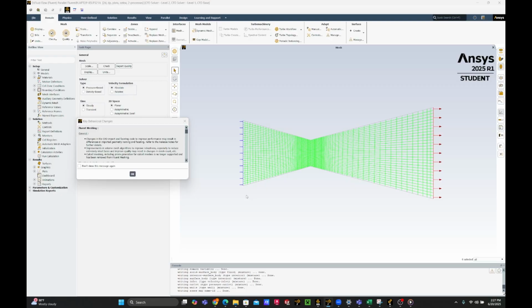Okay, perfect. And I know that this looks right because I have arrows going in and out, so that way I'm able to set up my pressure at the inlet and my pressure at the exit, and you can modify those. If you want a normal shock, you can just start increasing that back pressure or your exit pressure. And for the isentropic case, I just made the exit pressure your atmospheric pressure. So I'm just going to exit out of that.